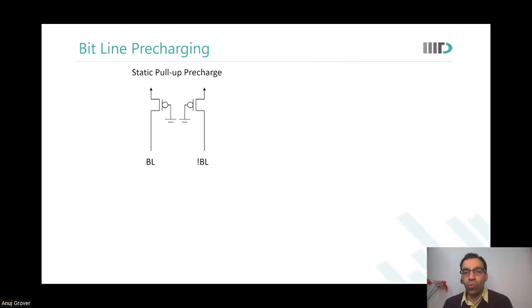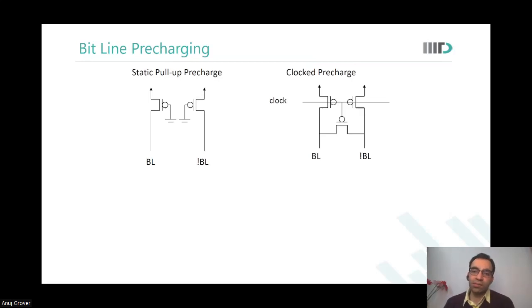So the alternate is clocked precharge. When the read operation or the write operation has to happen, only then the precharge would turn off. So now there is no race condition, or no ratio logic happening between the PMOSs of the precharge and the bit cell, which is trying to sink current. Are you able to see how clocking would help? So this clock is for the read.